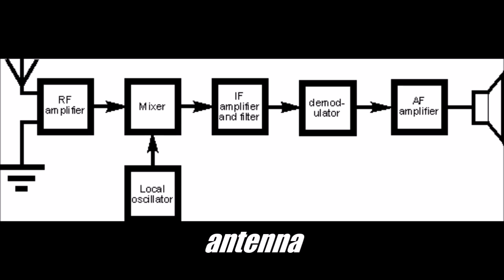The next component is known as the RF filter, which is also an optional component. It enables only selected frequencies to pass through it to the next components, while it rejects the other frequencies which are not required. The ideal filter will exhibit no loss within the pass band, that is, the frequencies below the cutoff frequency. Above these frequencies, it rejects all other signals. Moving on to the next component.